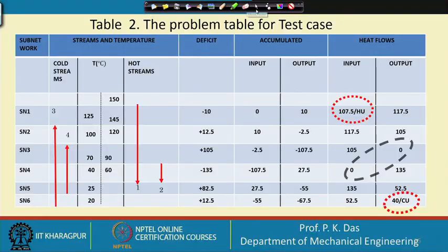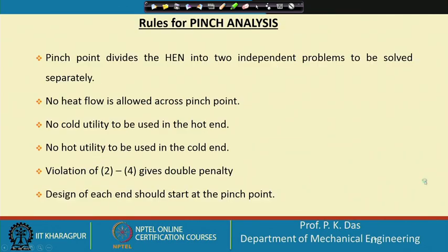Let us quickly go back to our slide. So, violation of 2 to 4 gives a double penalty, so this has to be avoided, and then the design of each end should start at the pinch point.